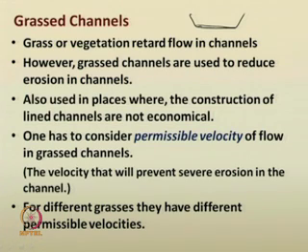So, generally grass channels are also used as a sort of lining, but this is a natural procedure. It can be used in places where construction of, for example, concrete lined channels or brick lined channels or mortar lined channels or wooden lined channels is highly costly and not quite possible, then you allow the natural growth of a certain type of grass in the bed of the channel, and consider this as a lining.